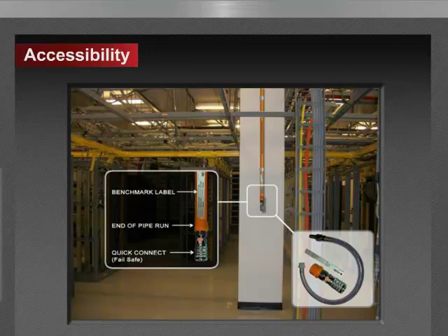But quite frankly, annual inspection is required of fire detection systems, including aspirating detection systems, or owners may have other requirements that exceed that requirement. The idea is that, as you benchmark test and you see flow differentials from the benchmark test at commissioning to your annual test, that might dictate cleaning the pipe.